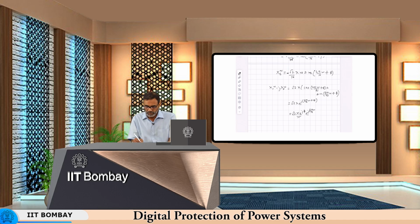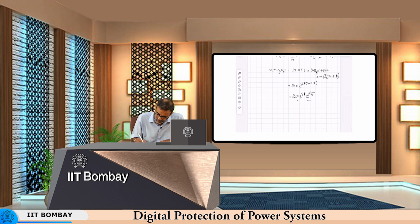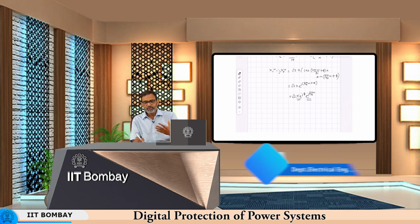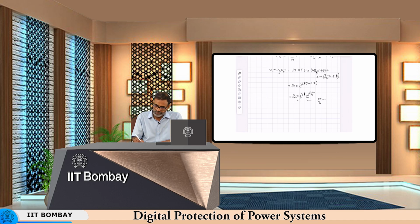Okay. So, what does this imply? Suppose we have got 12 samples per cycle. So, 2 pi by 12 is 30 degrees. What it means is that for every window increment, this phasor will rotate by an angle of 30 degrees. Okay. So, this is not desirable. The phasor itself is not changing, this is not the phi. Even if the phasor is constant, it will appear to be rotating because for every new window it has been incremented by 2 pi by N. Okay. So, this is that extra expression that we are getting. How to get rid of this we will see in the next class.